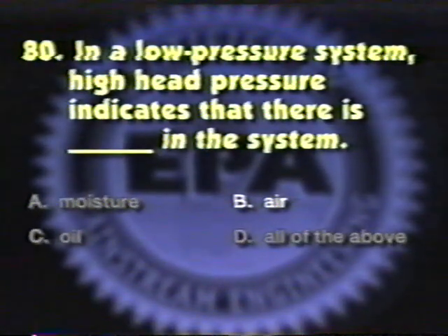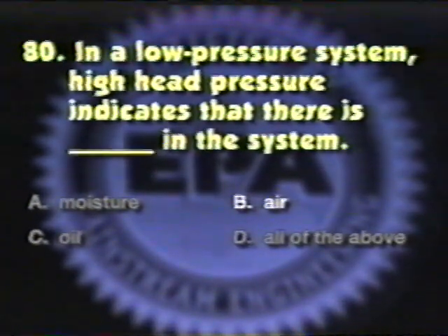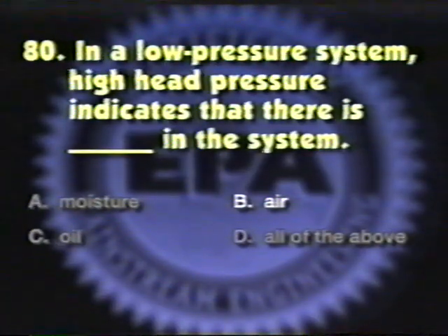The correct response is B. High head pressure indicates that there is either a lack of condenser cooling or non-condensables, such as air or nitrogen, in the system.